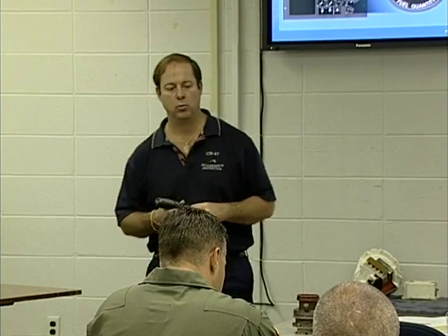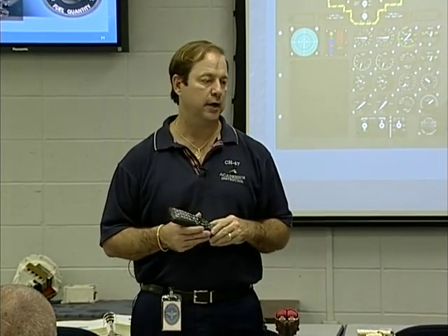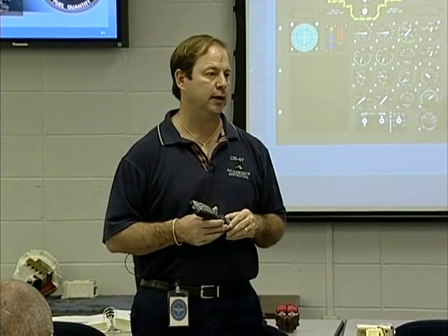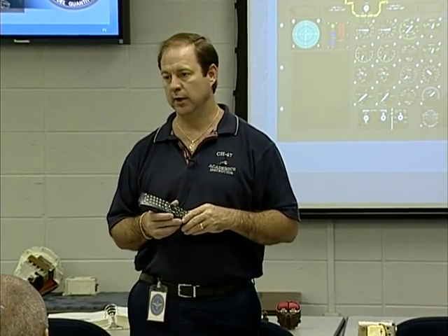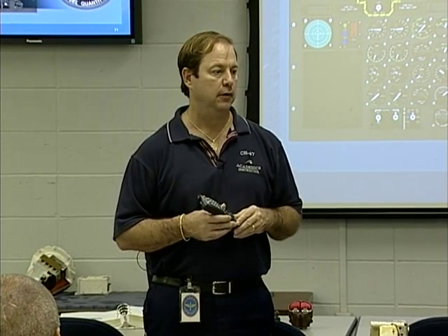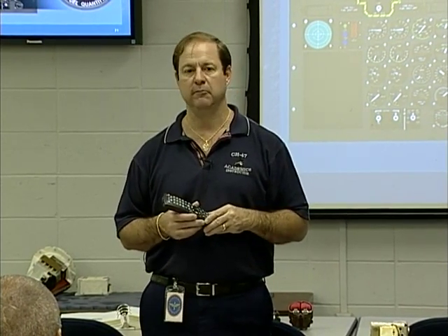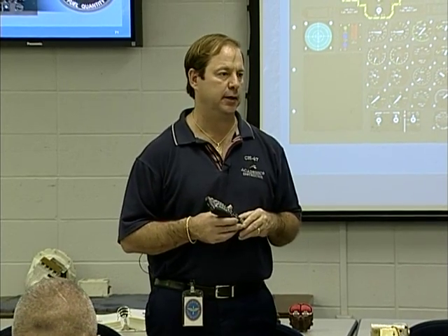I.e., if I'm going to carry a 1908 and I only have 5 minutes of flight time, I know that I cannot get to a 1908 with a full bag of gas and hope to pick it up. The gun itself and crew with an 822 bag is 19,200 pounds. If I don't burn off a sufficient amount of fuel, by the time I get to that weapon system, I'm not going to be able to pick it up.